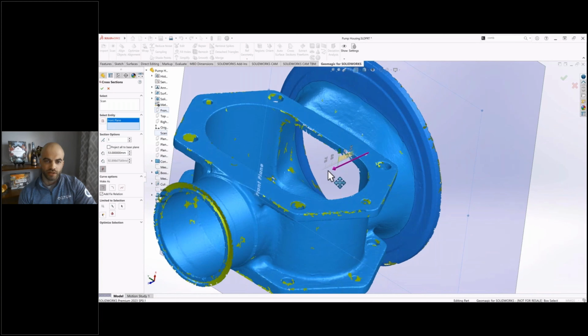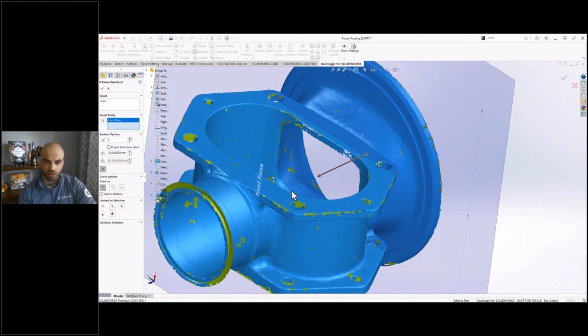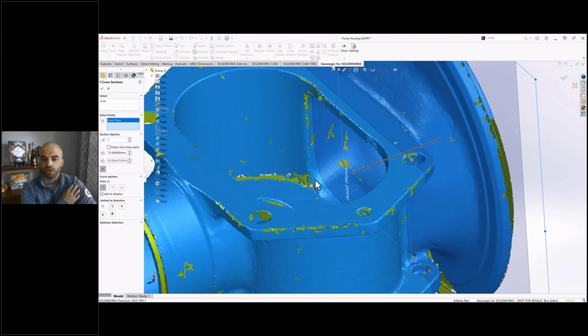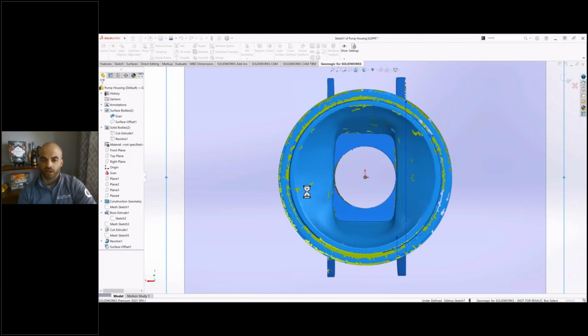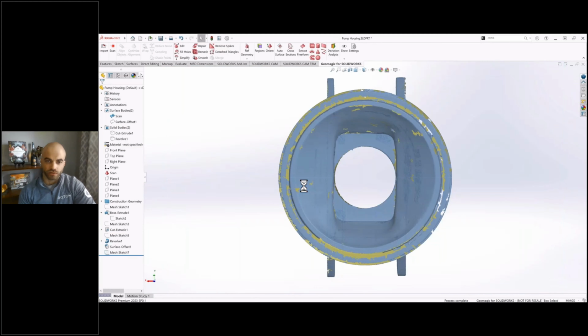At this point, I'm just guessing and checking and seeing what kind of an offset would be correct from the front plane there. We're at 73, we're getting closer, dragging it around, not quite there. And we'll land on 80 here. And that looks like it's about right. Again, it could depend on if you are modeling it perfectly or you're really trying to get, obviously millimeters versus inches would make a difference here as well.